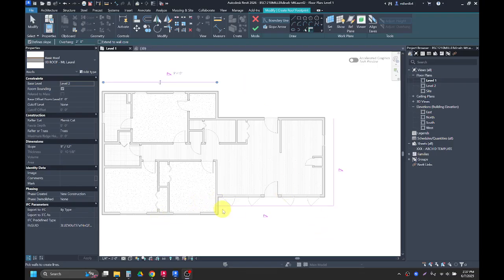That's okay. We can just manually draw that line in. I'm going to use the trim extend tool to bring these 2 corners together. So again, that's keyboard shortcut TR. And then I could click on these 2 lines and it'll bring them in to make that covered porch.